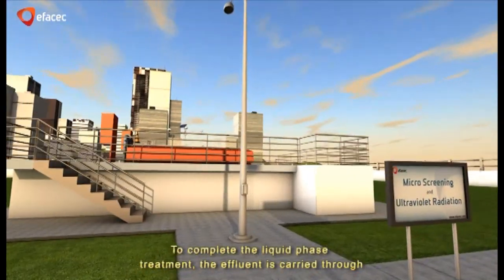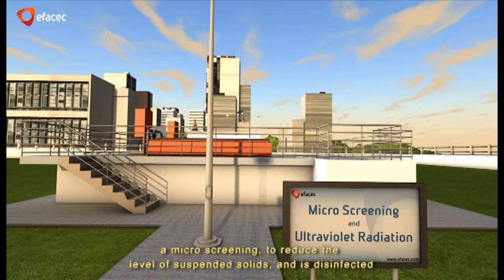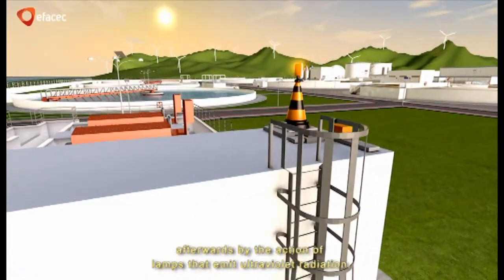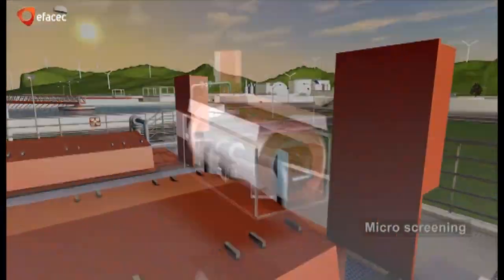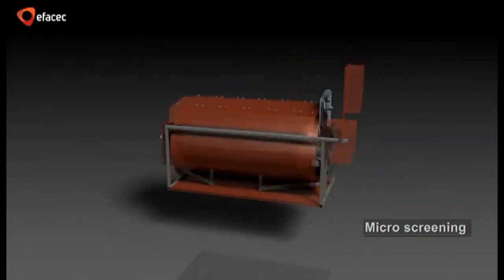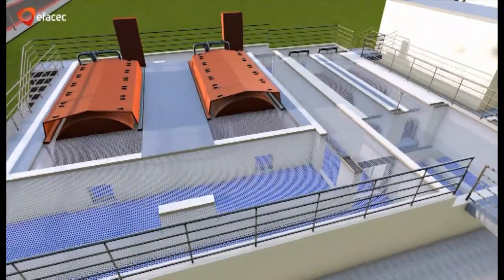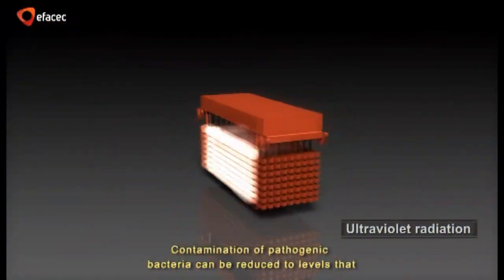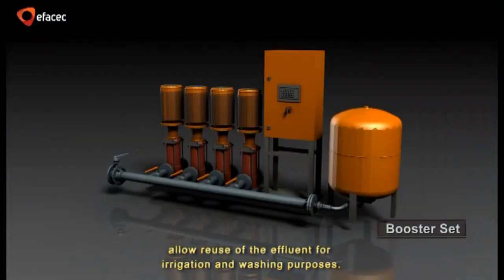To complete the liquid phase treatment, the effluent is carried through a microscreening to reduce the level of suspended solids, and is disinfected afterwards by the action of lamps that emit ultraviolet radiation. Contamination of pathogenic bacteria can be reduced to levels that allow reuse of the effluent for irrigation and washing purposes.